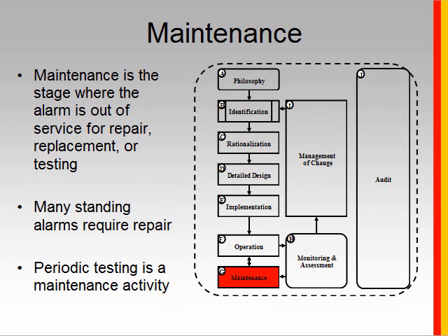If you've got a safety alarm, for example, you don't want to just take that alarm out of service and not think about the ramifications of not having that alarm. You may need to put in an auxiliary alarm to take the place of it temporarily until that original alarm is fixed. So there's a lot of thought and a process that needs to go into the safe maintenance practices and then putting them back into service.